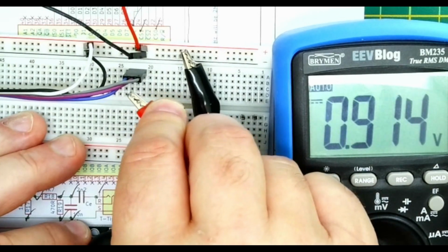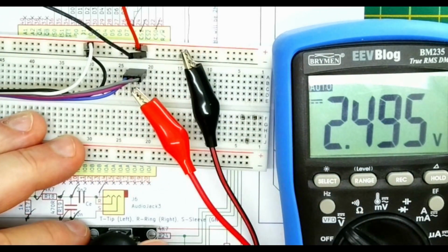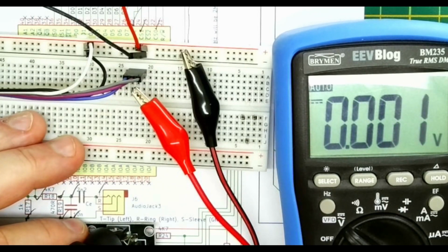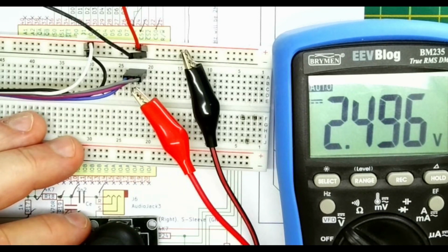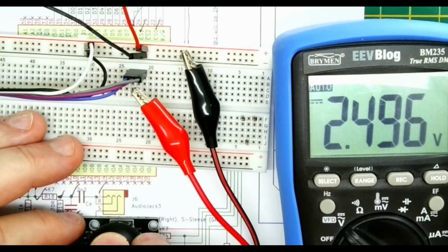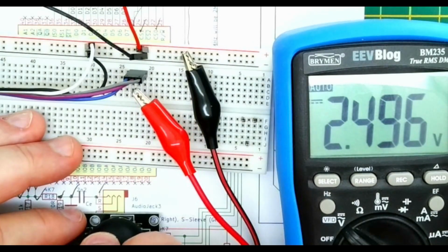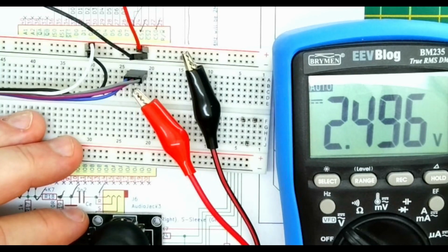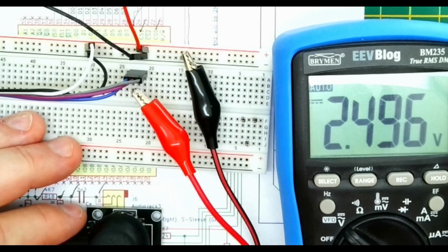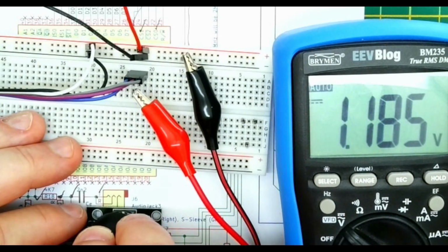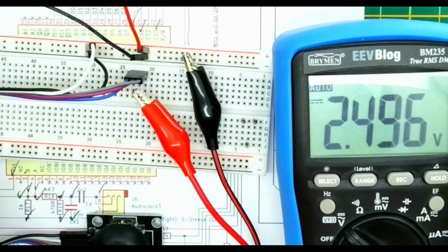If we plug this into the grey lead, which is X, we'll see again it's just under 2.5 volts. To the left is 0, to the right is almost 5 volts. So what we really want is for it to only start showing left once it's a little bit away from the middle. We need to set a threshold around the centre position, and we only want it to change after that centre threshold. So probably about 20% of the voltage or something would be good. Okay, so now I'm going to look at the comparator, and how we need to do that.